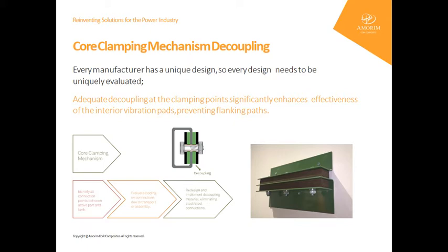And it's important when designing these solutions that we don't offer any standard solution for our customers. We give some guidelines for the technical and mechanical departments to design the final solution, because every company has its own transformer design. The guideline we give is that the material used to decouple the metal connections should not be too compressed, too stiff, in order not to have a rigid connection. So the material should be compressed around 10% as a guideline in order to have a flexible connection. That's what we want, to create a flexible connection.